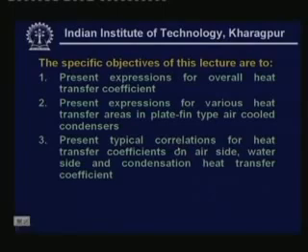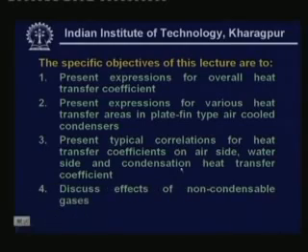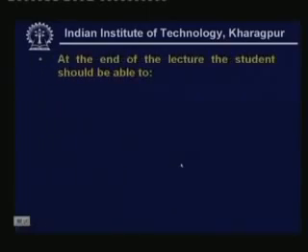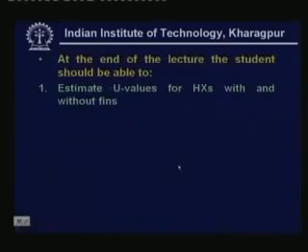Welcome back. The specific objectives of this particular lecture are to present expressions for overall heat transfer coefficient, present expressions for various heat transfer areas in plate fin type air cooled condensers, present typical correlations for heat transfer coefficients on air side, water side, and condensation heat transfer coefficient, and discuss effects of non-condensable gases.